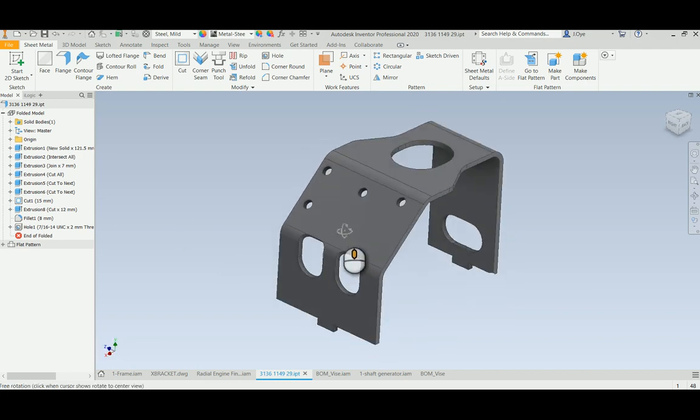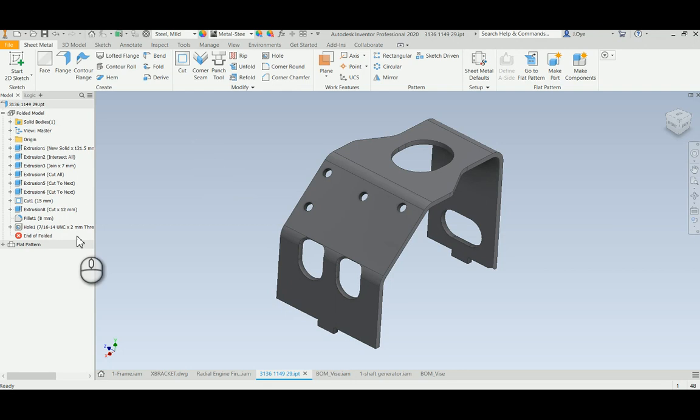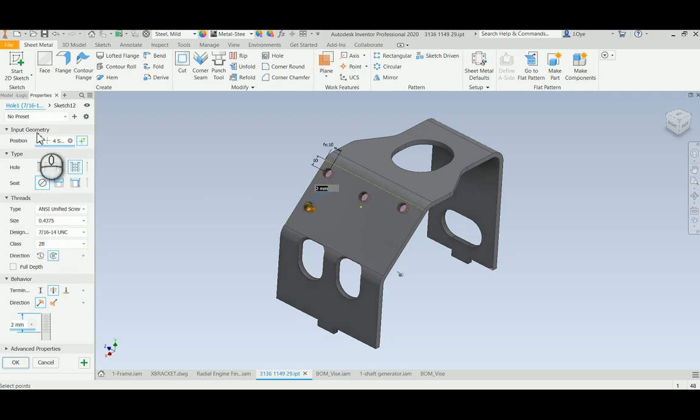Currently right now it's turned on. So what that allows me to do is if I haven't already placed sketch points on my surface, I want to place those holes. If I have it turned on, I can actually place additional holes on that surface. Prior to the release, this button did not exist, and really the only way that you could place holes at this moment was if you already had unconsumed sketch points on that surface. So really good addition to be able to have that toggle button where you can keep adding additional holes.